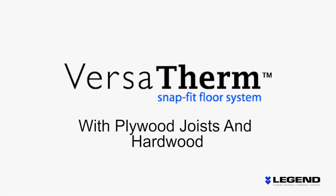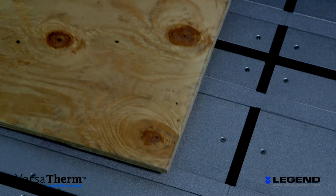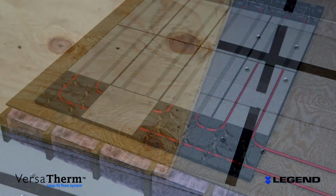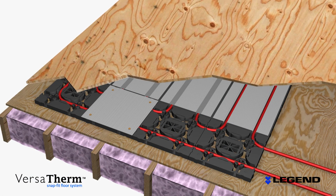When using VersaTherm with a hardwood floor, the VersaTherm layer is sandwiched between the subfloor and the nailing surface for attaching the hardwood. The nailing surface is typically 3/4 inch plywood, thick enough to accept and secure the hardwood flooring planks. Be sure to mark where your tubing channels are before you start to screw down the nailing surface and VersaTherm layers.